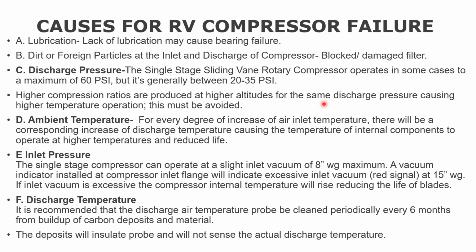Ambient temperature: for every degree of increase of air inlet temperature, there will be a corresponding increase of discharge temperature, causing the internal components to operate at higher temperature and their life will be reduced.